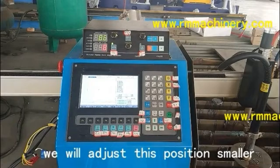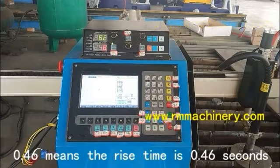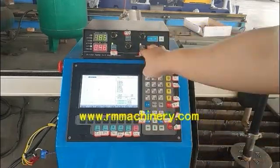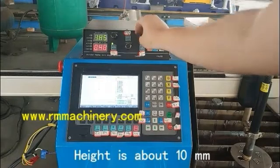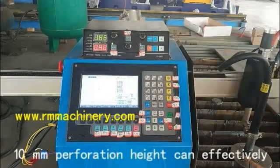Let's see if it is larger than 10 mm. We will adjust this position smaller. 0.46 means the rising time is 0.46 seconds. Let's try again. Adjust to 0.4. Height is about 10 mm. A 10 mm perforation height can effectively solve the nozzle burnout problem.